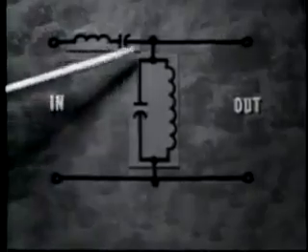The pi section band-pass filter can be constructed by, again, maintaining total circuit inductance and capacitance values the same as in this basic L section. We'll add an additional shunt leg to the basic L section like this. We now have two capacitors in parallel, so each capacitor must equal half the original capacitance. 1/2 here and 1/2 here.